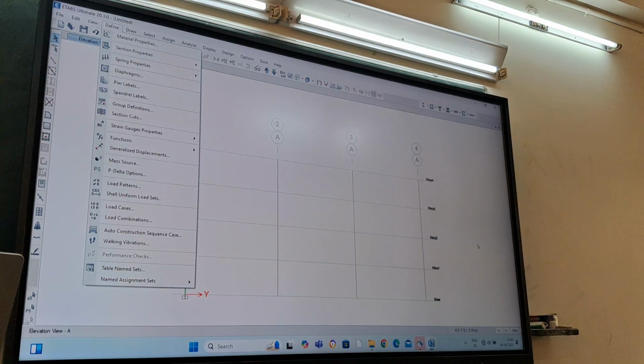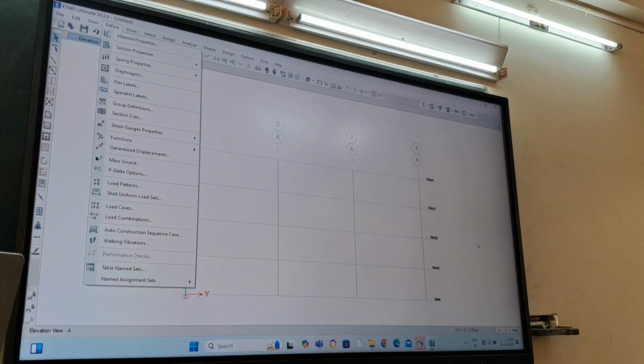We have a target displacement of 200 mm. Now, what load path this 200 mm will follow, that we have to assign. Maybe it can follow a time history similar to an earthquake, and the peak of that time history will be 200. Or maybe it will follow a linear pattern, meaning a triangular load path. It will start from 0, then linearly increase up to 200. So we will define one time history for that.